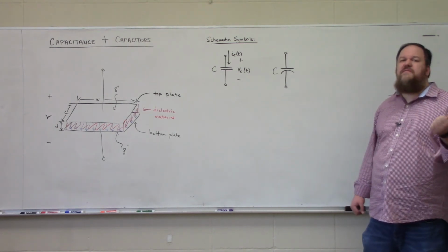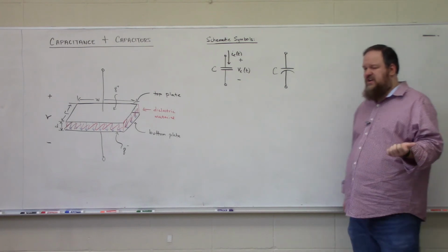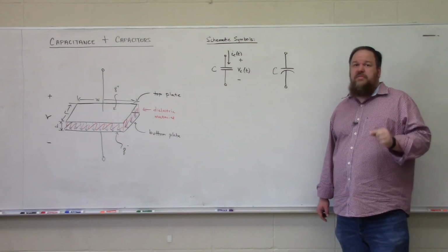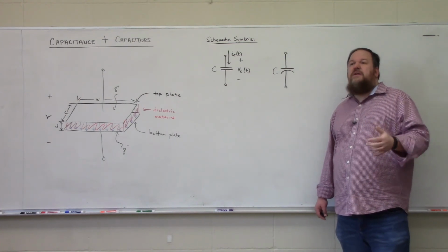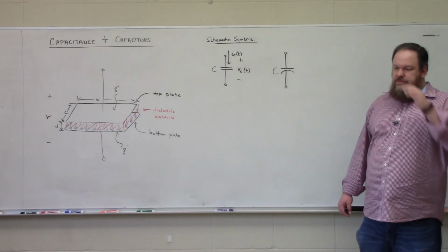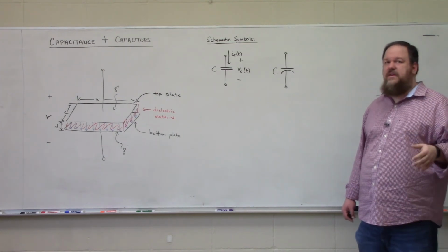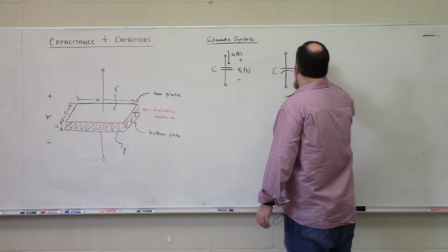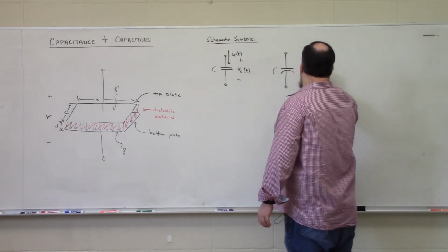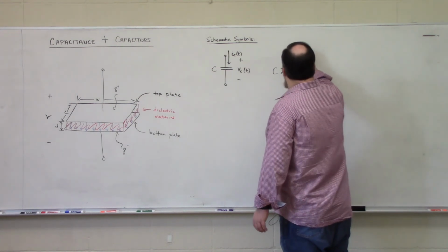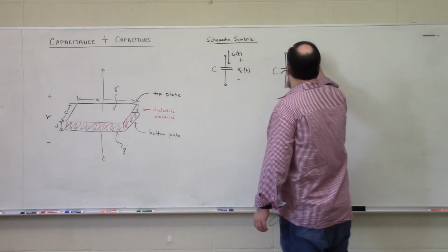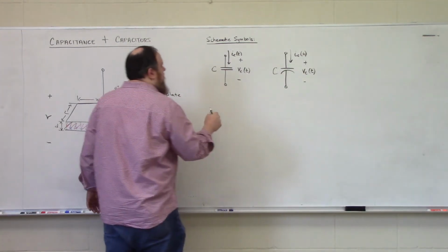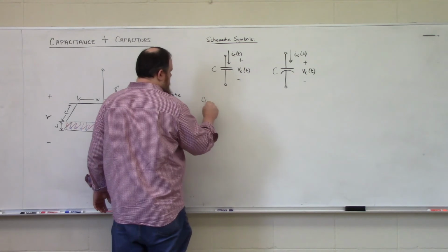So it's a trade-off. You get very high capacitance values out of electrolytic capacitors because the dielectric layer is so thin, but they're very, very prone to misuse. You have to pay explicit attention to the way that you're connecting them, or you'll break them very easily. And an electrolytic capacitor obviously also follows the passive sign convention. So now, let's talk about our current voltage relationships.